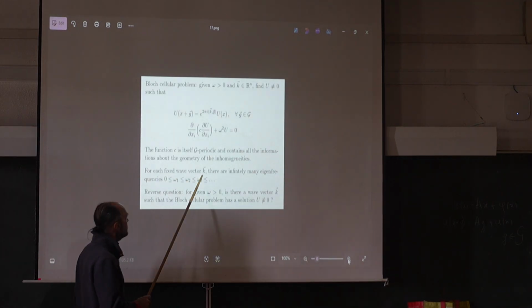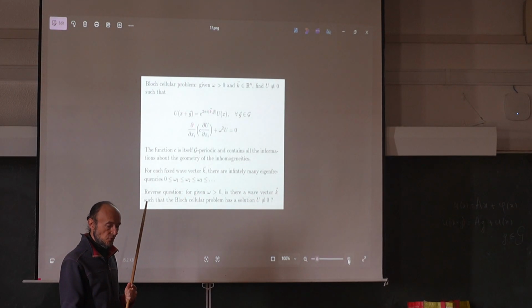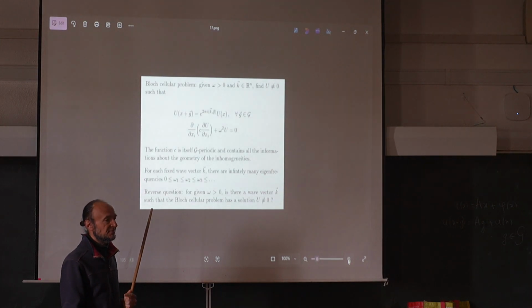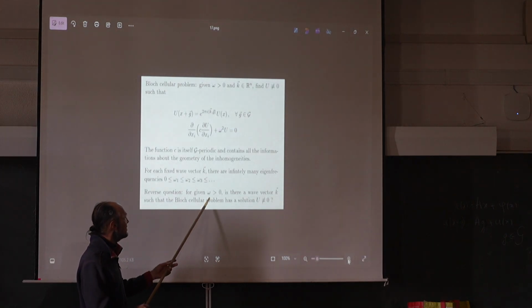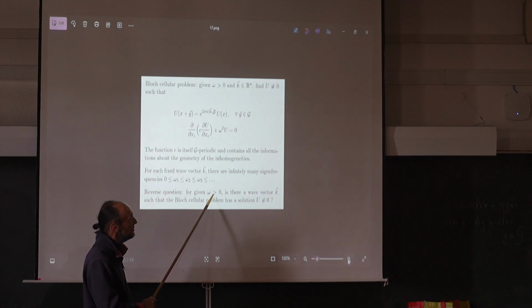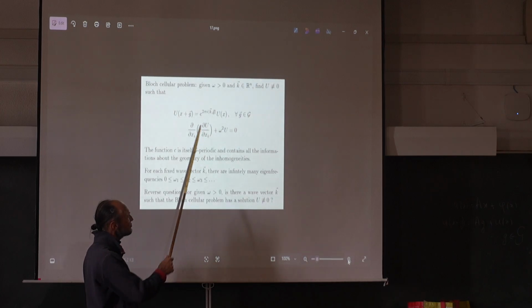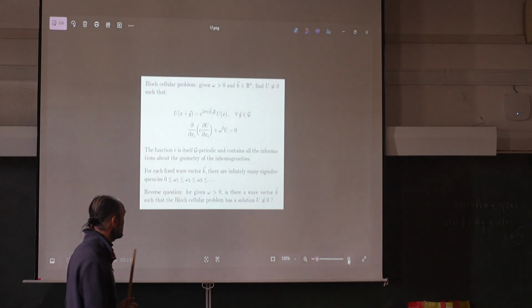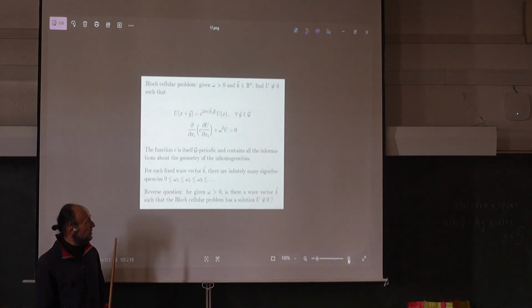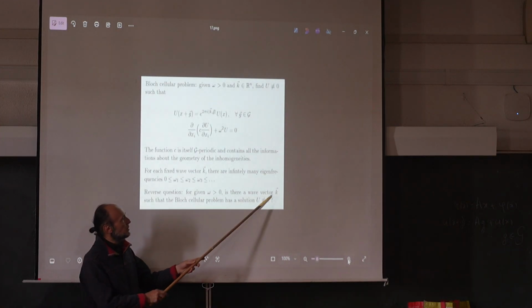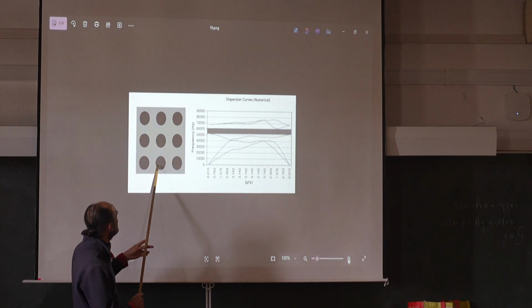So for each fixed wave vector K, you get different manners of the wave propagating with that wave vector. But you could also reverse the question. If you choose omega to be the angular frequency, can you find a vector K such that the propagation is like this? And the answer is surprising, because sometimes for certain geometries, for certain microgeometries in the cell, there is no solution, there is no K associated to that omega. So you obtain band gaps.